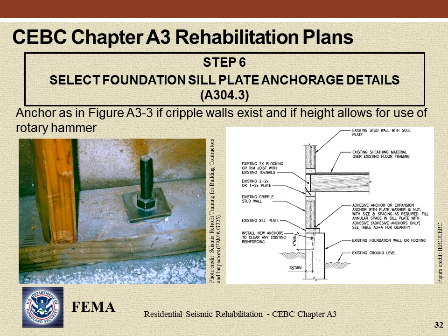Where sufficient height exists, the simplest anchorage approach is to install anchor bolts using adhesive or expansion anchors. The anchor hole needs to be installed using a rotary hammer, which requires significant height at the cripple wall. For moderate and low wall heights, alternate details are usually used.